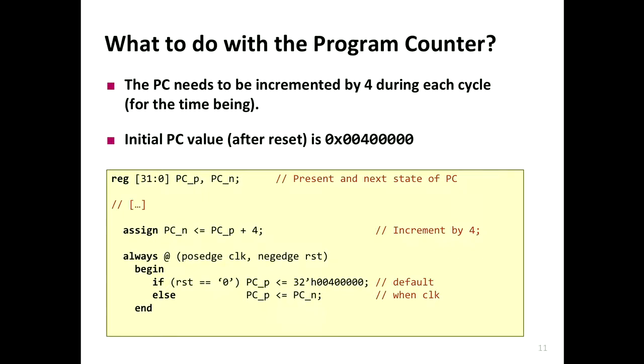That is one answer, but there are also other answers about how these transistors were implemented in the technology. You can say it is to prevent glitching of the circuit, because it's an asynchronous reset. If it was a synchronous reset, it was fine, because the glitch has to happen exactly along with the rising edge of the clock; only then will the system reset. It's much more rare. But with an asynchronous reset, at any point when you have a glitch in the circuit, your system is going to get reset. So it's just for more stability purposes, among other reasons.